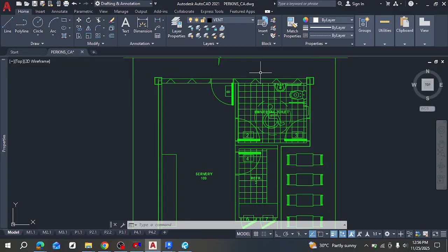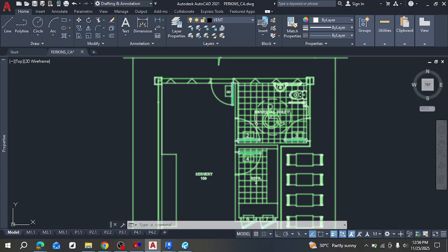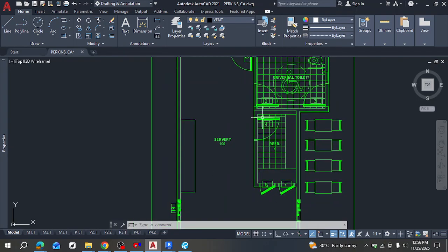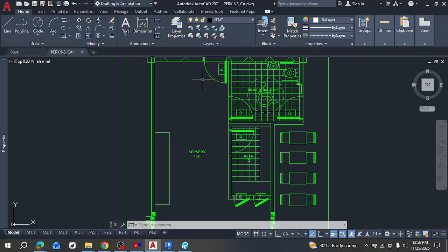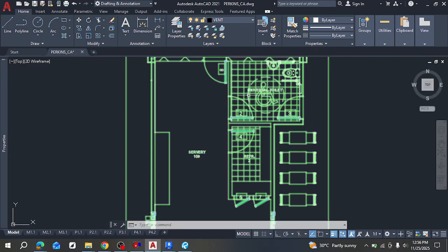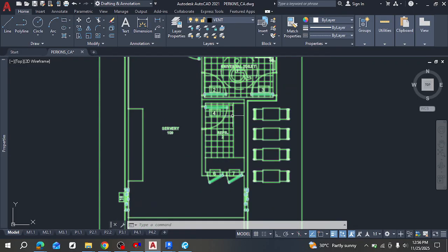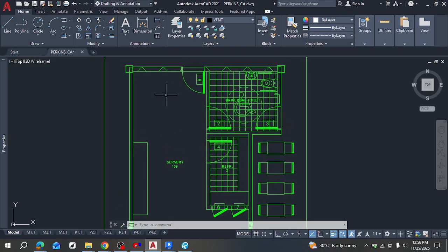That's also why I selected a rooftop unit for this project. And also, usually commercial buildings have a mechanical room to place equipment, but in this case there's no such room. So that's another thing that made me select a rooftop unit. So now it means you have selected a 3 ton rooftop unit for this project.